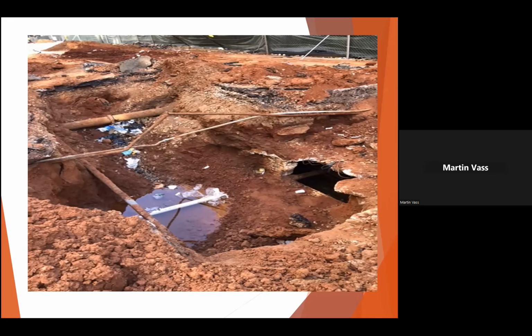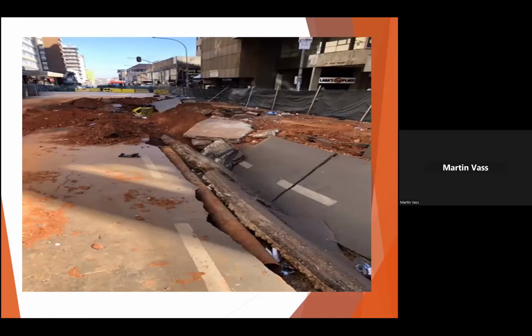Again, there wasn't a problem. The culvert was aerating, it was ventilating through the manholes. But because of cable theft, the manholes were then welded down. So then there was no escape for the methane. The methane built up and there was an electrical spark and it went bang. So this, in fact, was a methane explosion. It wasn't a gas explosion per se. It wasn't a gas explosion from Egoli Gas. But it caused a huge amount of damage, as you see.